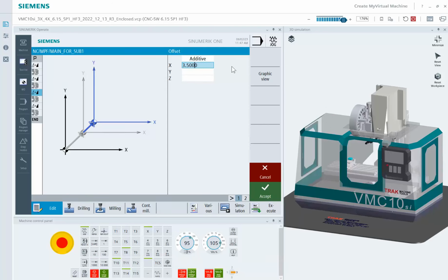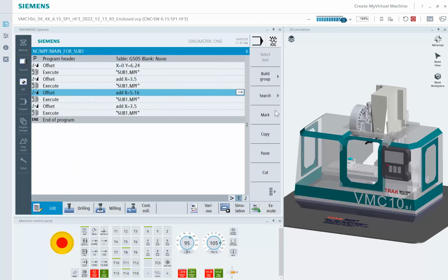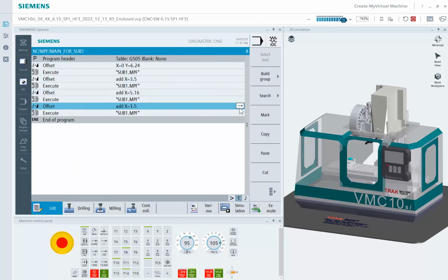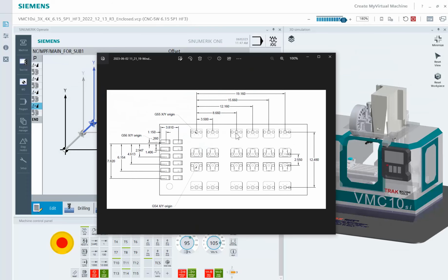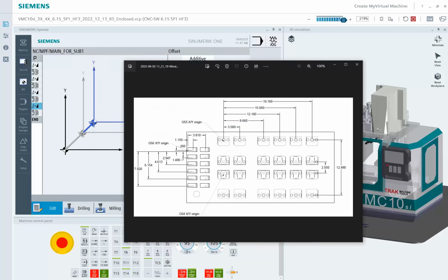So I want to do, print says 8.66 minus 3.5. So there's that new pitch. That's going to get me hopefully the 4th. The 5th, and keep in mind I'm always working, because it's additive, to my last 0 shift. I now have to subtract 8.66 from 12.16.